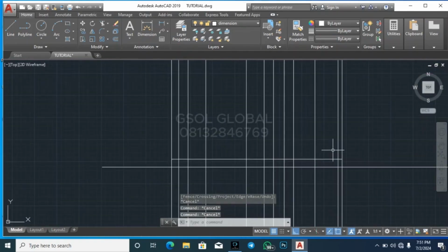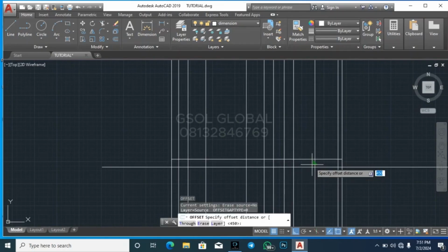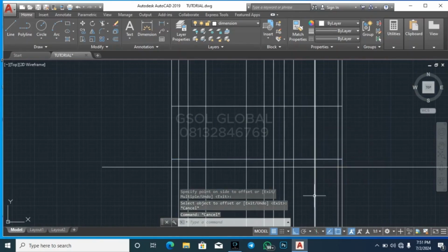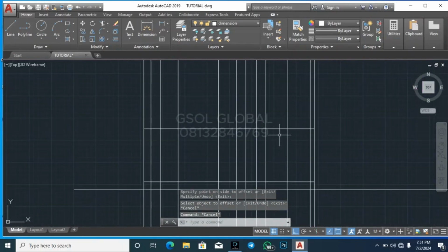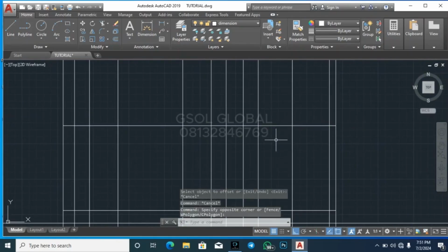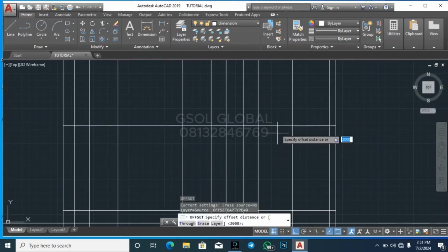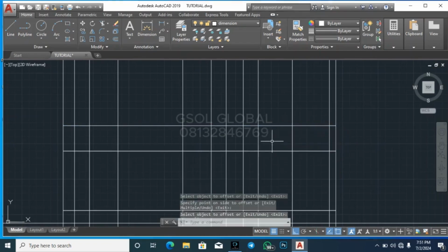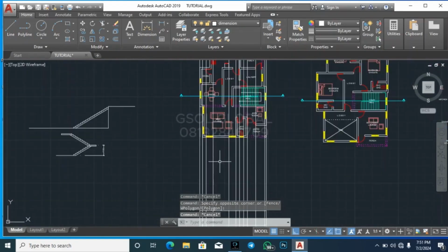All right. So the next offset we are going to be doing is an offset for the headroom. From this point onward, we'll be having a headroom offset of, let's say, 3 meters. Good. So now the next one we're going to be doing is an offset from the top, from this point 900 downwards, for the boundaries of our windows and doors. All right, so now let's check for the ground level.